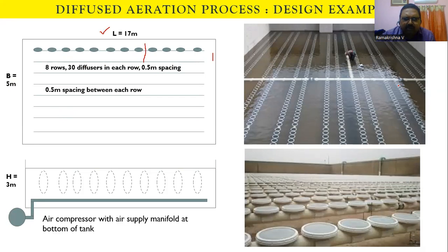Now in the picture you can see this is how the diffusers are going to be arranged. So there are 1, 2, 3, 4, 5, 6, 7, 8, 9, 10, 11, 12. There are 12 rows here, and the number of diffusers. Now in the bottom picture you can see the diffusers are placed here, with some center to center distances. So here the circulars are there, but what we are taking is 0.3 meters square sections.